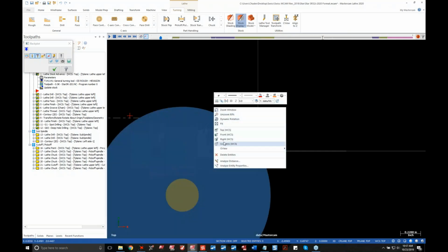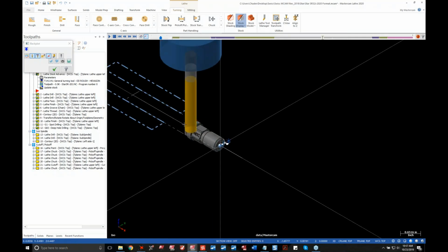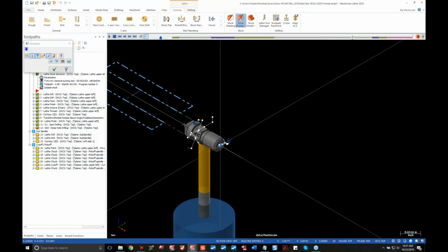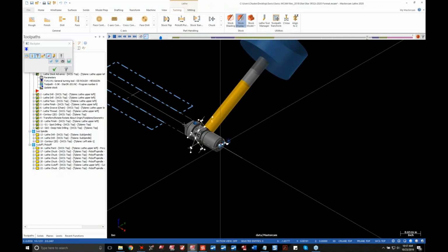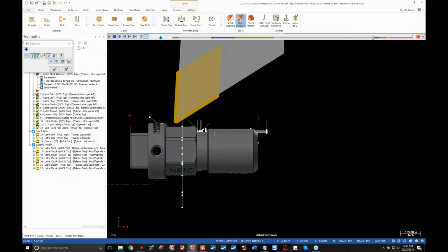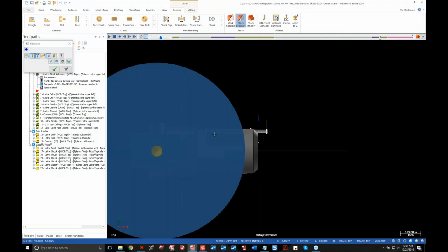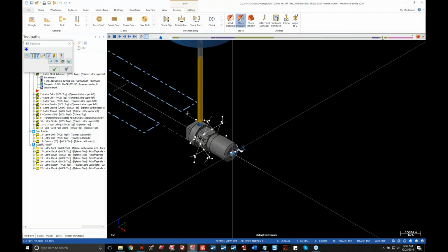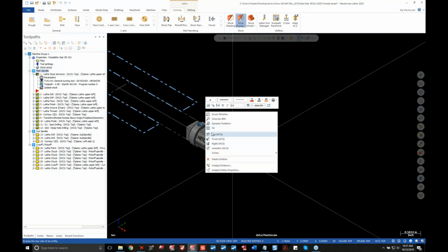Then we're using the milling side, which Matt spoke of. You need Mill and Lathe for this because of the capabilities of the machine. You need both licenses. So this is using the mill. We're coming in here and milling around these flats on the hex on this part. And then we'll top off the shoulder back here, then drill a cross hole in it. So we're spotting it and then drilling it. Okay, so that's pretty much everything on that first side.